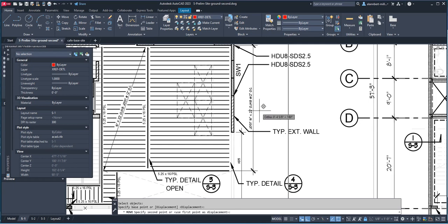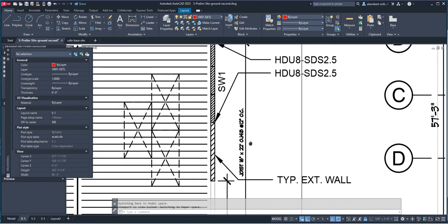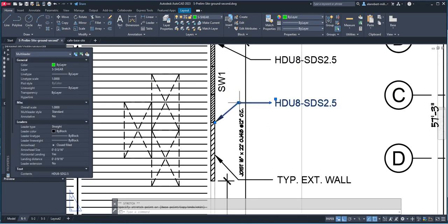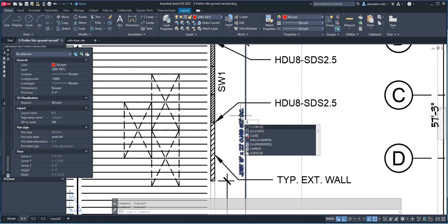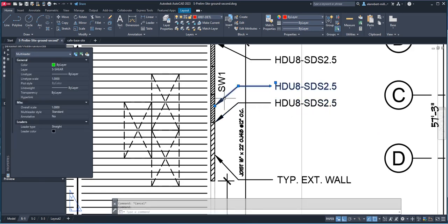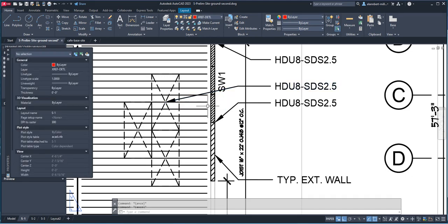Yeah, like that. Okay. And then we're gonna call this out. You just have to be good at where would you put that note. And maybe I can bring this no space in the paper space, click this and pull this down. And then maybe I can simply do a copy of this leader, bring it up a little bit, and then bring up the edge to the intersection of that one.